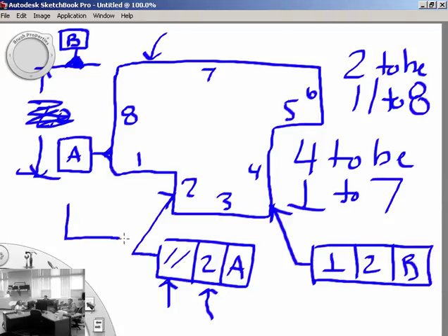By the way, feature control frames typically don't change directions much. A lot of times they will back angle the arrow like I've done here. But this one will only require 2 boxes. Just for reference. Now, what goes in the first box right here? Straightness symbol. That one right there. Just one little horizontal line is your straightness tolerance.